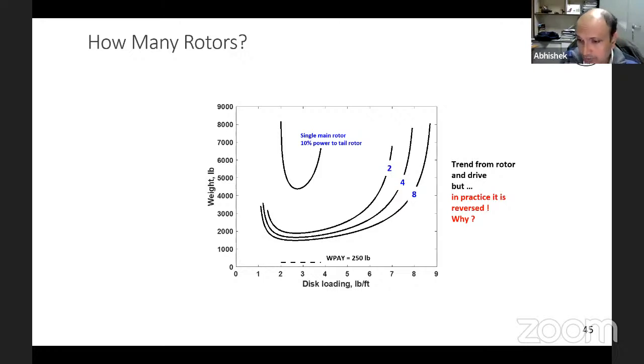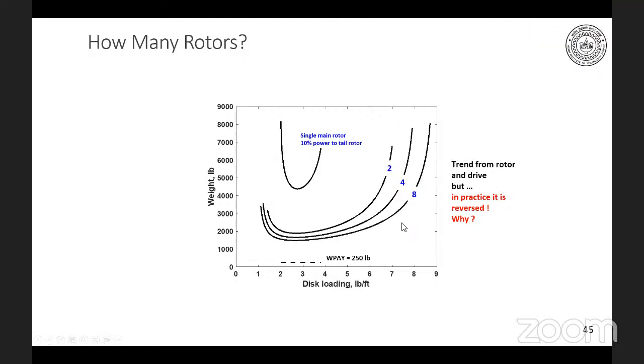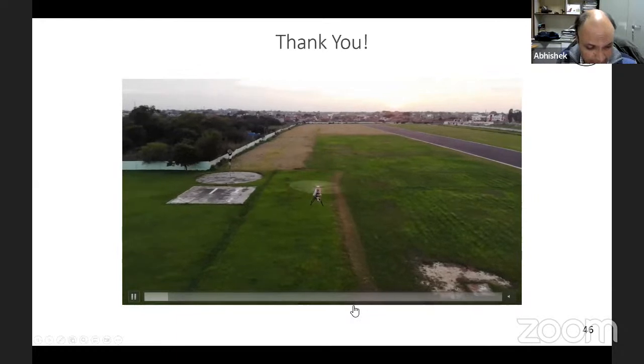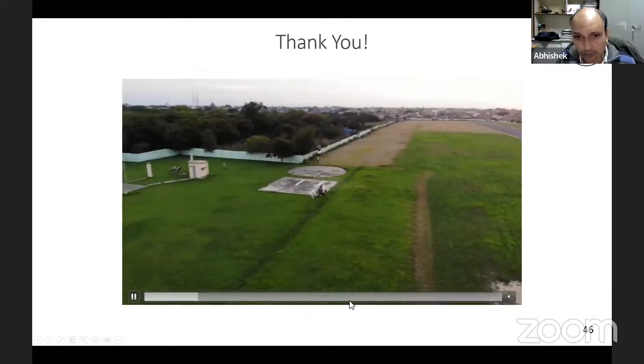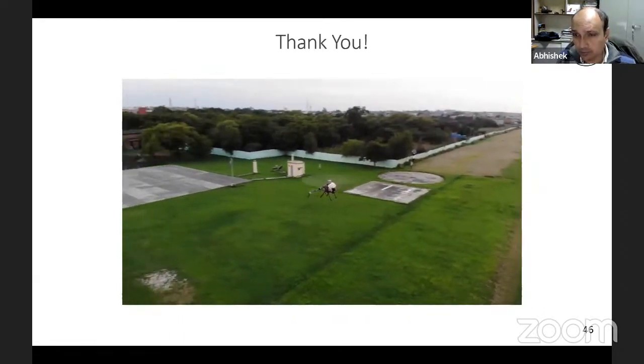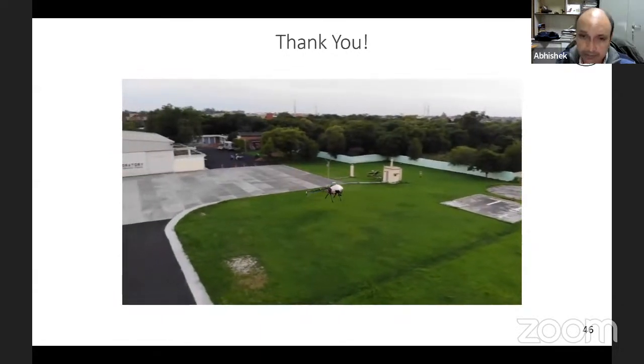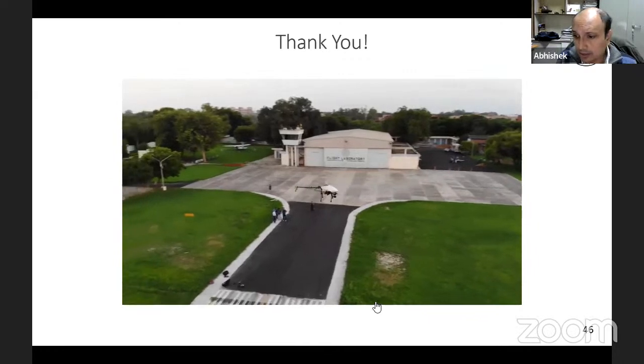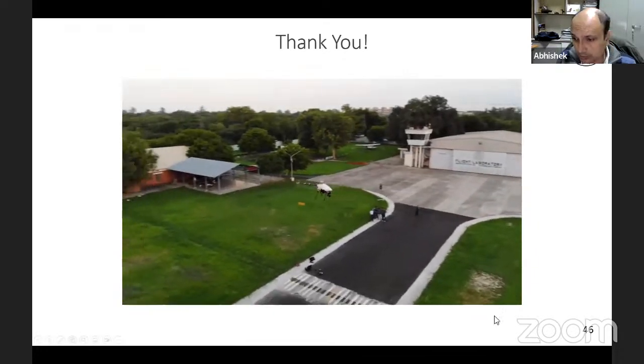the way it is happening in Volocopter and so on, where they have 20 odd or 16 odd propellers, and with that many propellers, you have so much airframe which is to be added, and it adds to the weight, and it also adds to the drag. So your drag will increase significantly because of that. So that is all from my side. Okay, so that's what I wanted to give you, a quick snapshot of the whole design process for VTOL vehicles, how a typical multi-rotor or VTOL vehicle is designed, and I'll be happy to answer any questions that you have.